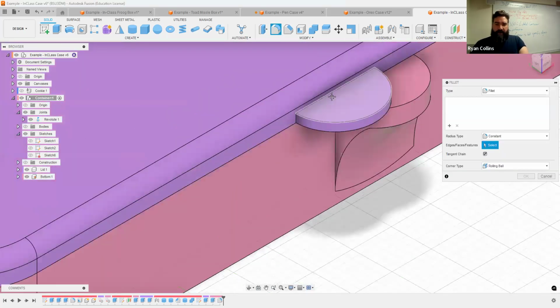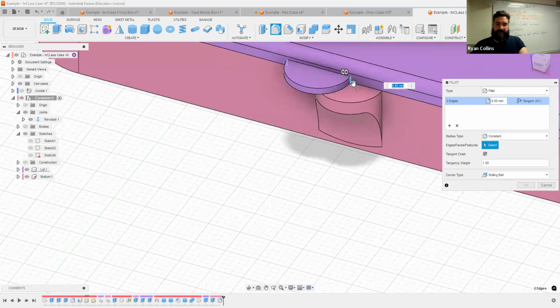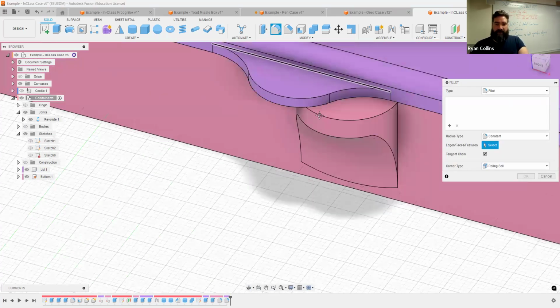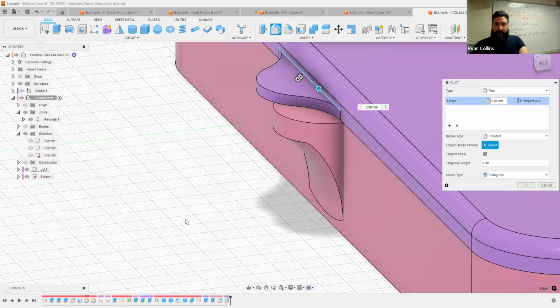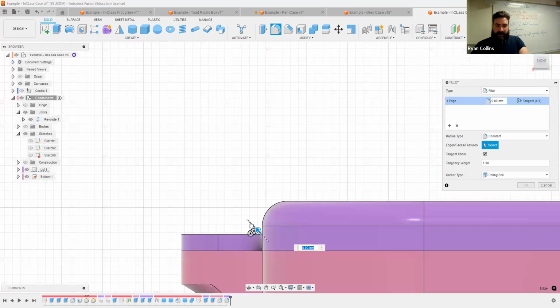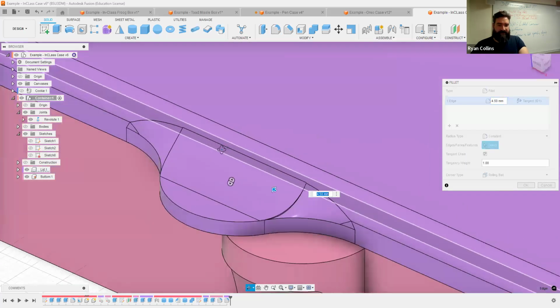Little fillet up there. And on this one, I'll show you a couple other things you could do. Let's first start with filleting just those two corners, and I can drag this outward. Weird. Hit OK. Now repeat the fillet for that now extended part. Now I'm not going to be able to push this too far because I am working on a very small lid here. But as I drag this outward, I'll drag it until I get an error. Right there, so 5. So apparently more like 4.5. Oops. And I can get this kind of interesting shelf there.